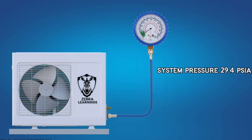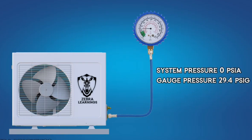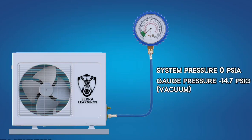If the system pressure is 29.4 psi absolute, the gauge will show 14.7 psi. If the system pressure is 44.1 psi absolute, the gauge will show 29.4 psi. If the system pressure is 0 psi absolute, the gauge will show minus 14.7 psi, which is vacuum. So, you can see, every time we add or remove 14.7 psi, it shifts between absolute and gauge pressure readings.